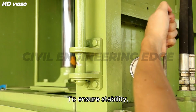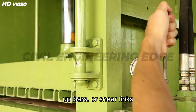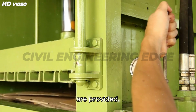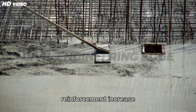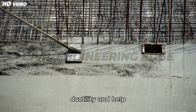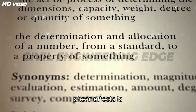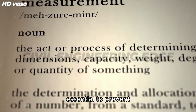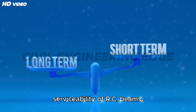To ensure stability, shear reinforcement like vertical stirrups, bent-up bars, or shear links are provided. Proper detailing and spacing of shear reinforcement increase ductility and help redistribute stresses. Hence, understanding shear effects is essential to prevent premature failure and ensure long-term serviceability of our RC beams.